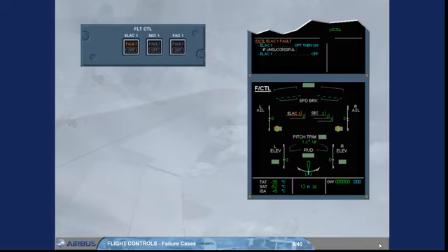Also, on the flight control panel, an amber fault light is on, helping you to locate the push-button switch relative to the ECAM procedure. But, according to the computer reset procedure, described in the QRH, or FCOM, a computer can be reset by its push-button switch, or by its circuit breaker, CB. Note: usually wait 3 seconds if a push-button switch is used. Or refer to your documentation if a CB is used, as it will depend on the computer.